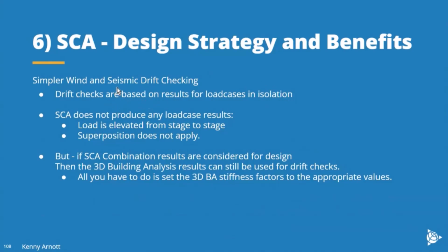The way you can do this with stage construction analysis, and what we need to remember here is that stage construction analysis doesn't produce any load case results. As I've described in a previous webinar, the load is elevated through the construction stages to get to the end of construction, and then you elevate it again up to design loading levels. And you can't readily go back down to only a load case by load case level, or it can start to do strange things if you do that sort of thing.